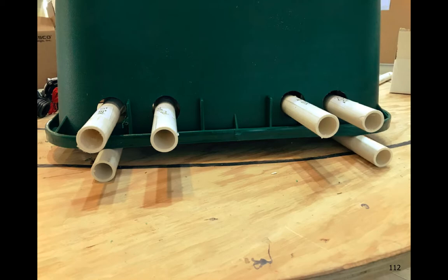In this case, we want to give ourselves a little bit of room to do some plumbing, so we suggest cutting a couple pieces of 1-inch pipe, placing them on the tank, and then putting the headworks on the pipe. Unfortunately, if you just do this, the headworks is going to want to roll around. So put a little bit of soil or some aggregates around those support pipes in the bottom so that they won't roll.